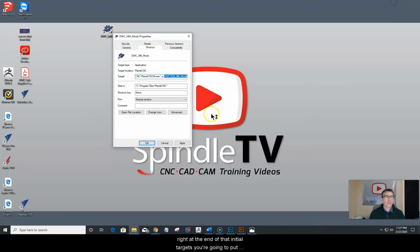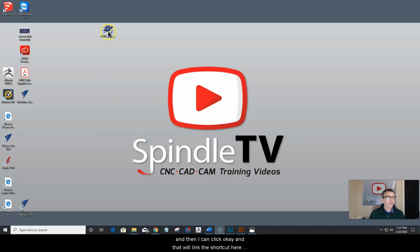Okay. So once again, right at the end of that initial target, you're going to put your mouse cursor, hit the space bar and type in that -p, another space followed by that profile folder name. In our case, it's capital DWC 1824 underscore mill with a capital M underscore mode with a capital M. Once I have that typed in, I can click apply, and then I can click OK. And that will link the shortcut here on the desktop to that profile folder.